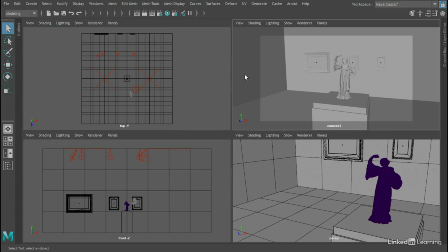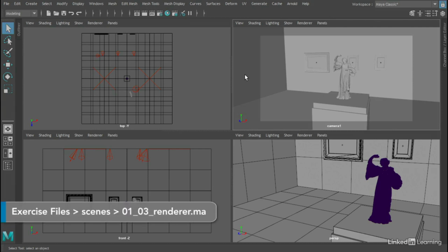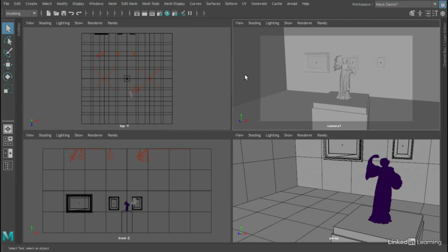As we'll see, the Autodesk standard surface material is physically based and designed to be renderer agnostic, meaning that it will work with almost any renderer. However, regardless of that, you're going to need to set up your specific renderer before you begin any material look development. And that's because you need to optimize performance as well as renderer options such as the ray depth. Otherwise, your test renders of materials may not give you an accurate representation of what you'll get in a production rendering. In this course, I'm using the Arnold renderer, which is the default in Maya.